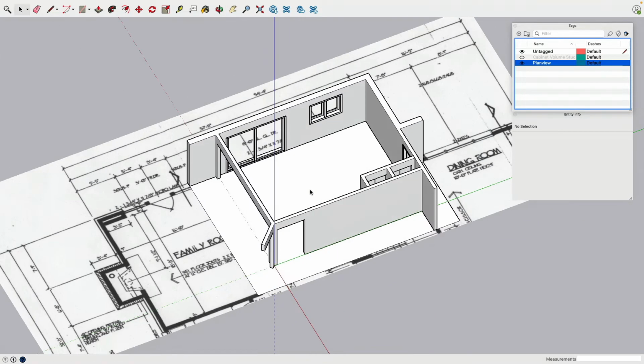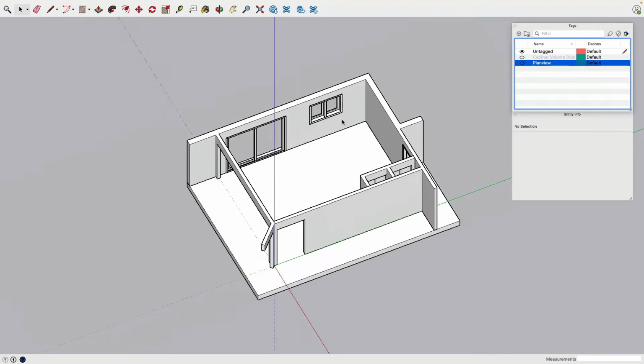You know, there is something called an AutoCAD drawing. That's great to have, but never trust an AutoCAD drawing you didn't create yourself. Because is this, for example, the original drawing? Is this a drawing that also reflects changes during construction? Is it a drawing that reflects changes when remodeling happened, etc.? So it's great to have those, but best is to take measurements yourself.